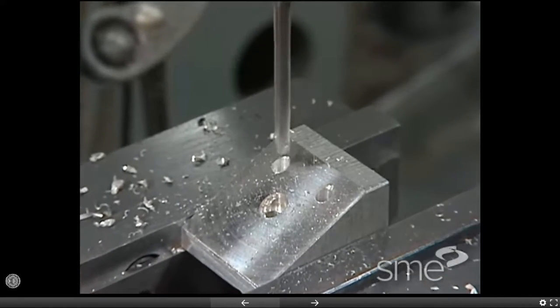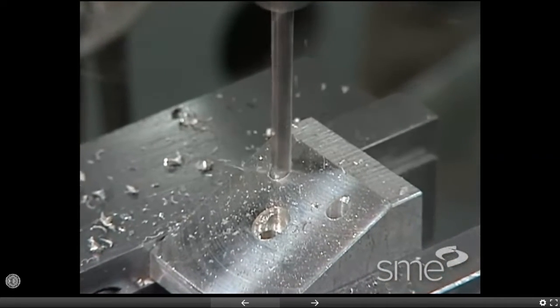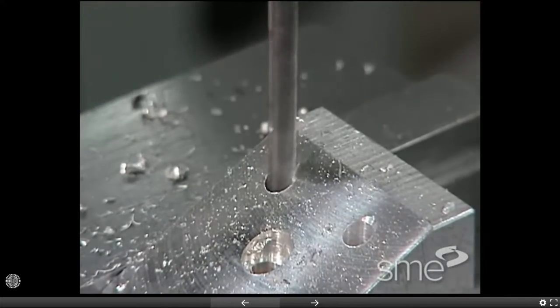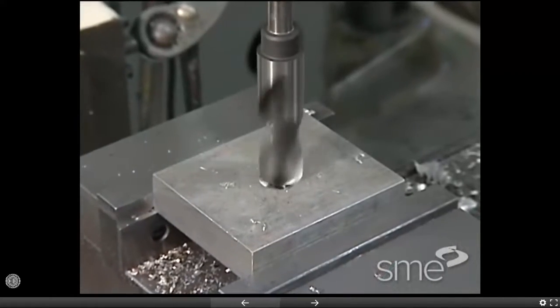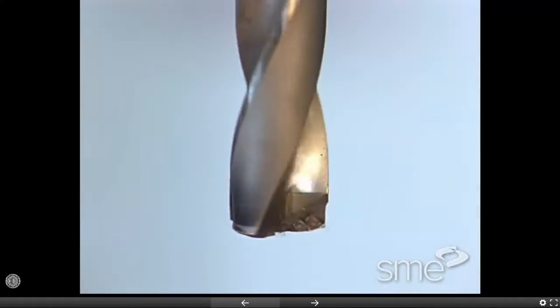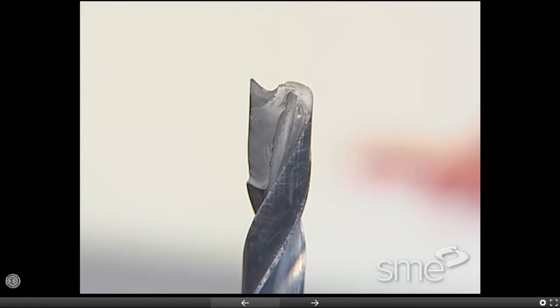Generally, the feed rate must be reduced, sometimes up to 50%, when drilling into curved or sloping surfaces, drilling across another drilled hole, or when enlarging a pre-drilled hole. Excessive feed rates can cause chipping or fracture of the cutting lips, as well as splitting of the drill's web.